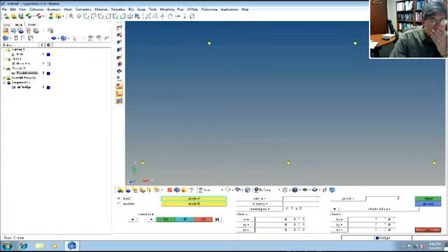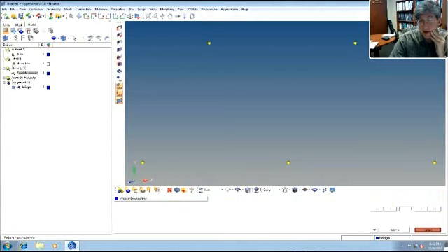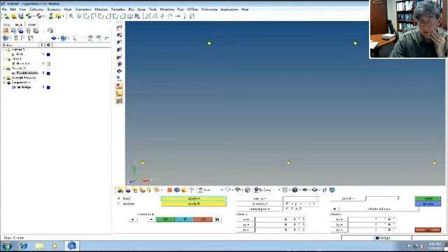All right. Now if you look at this menu, this allows you to define them. You pick the 2 grid points. You can pick the element type. These are going to be C-bar. You need to define the property card. So you click on that. You can see it allows me to choose one of the property cards I defined. I only have one, so that's it. Here are the pin release degrees of freedom, right? You can do the offsets at A and the offsets at B. We won't use those. And you can also, well, here's where you define the orientation vector.